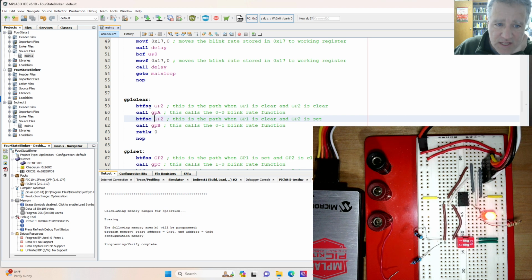So let's say it is set. Let's say GP2 is set. So that means it skips this and it goes to here. Well, if GP2 is set, then it's not clear, and so it won't skip that. So it's got to hit one of these two, and only one of these two. And so then we will call GPB. So this is going to represent the 0, 1 state. Had this been clear, then we wouldn't have skipped it, and we would have called the 0, 0 state.